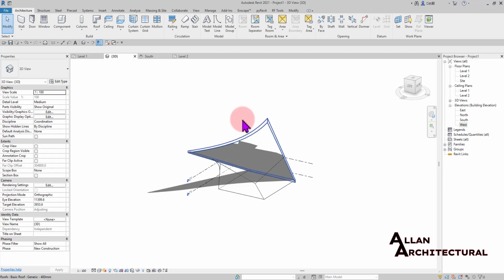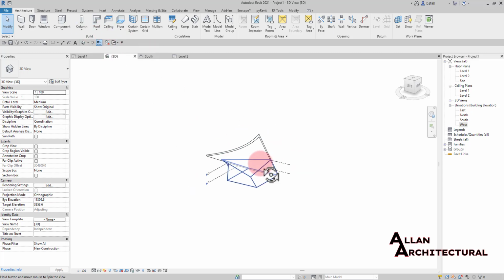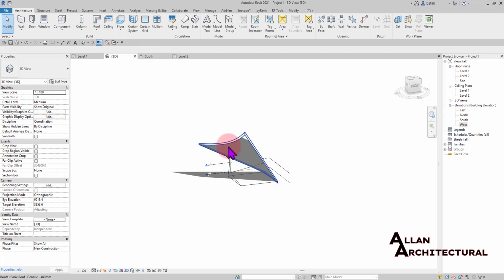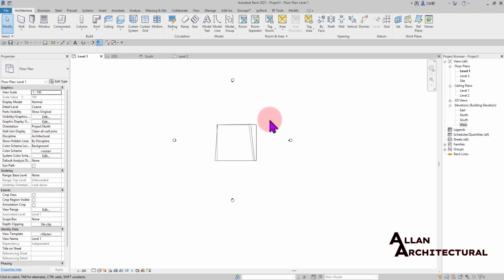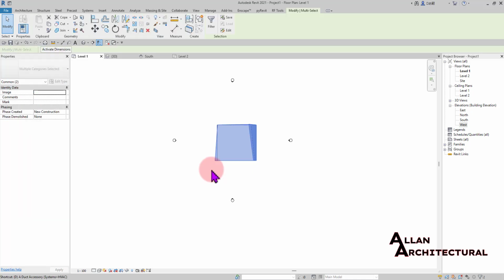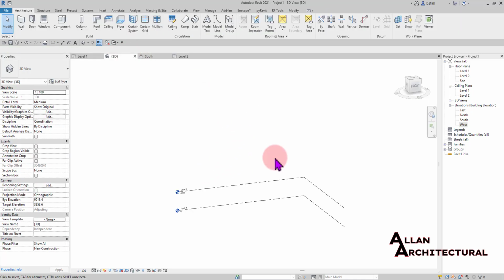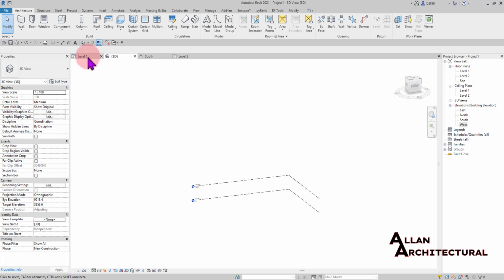Now I'm going to end everything in here, and I'm going to talk now about flat roofs. We are going to start talking about flat roofs and how we can create them, and also use our shape editing tools to create a slope in our flat roof to join to a drain. So I'm going to get into level 1 and delete everything out of the way. So DE on my keyboard, and I tend to lose everything in my file in here.